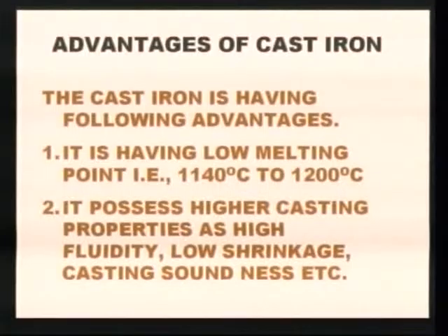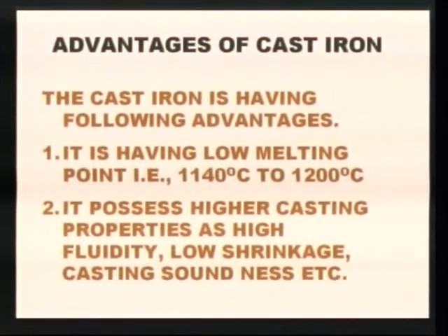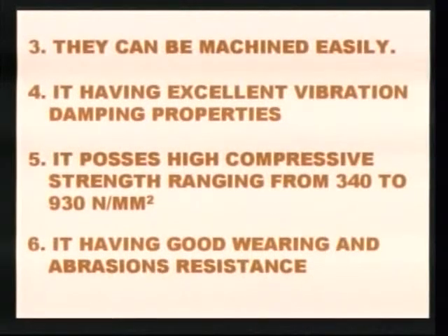First, it has a low melting point, that is 1140 degrees centigrade to 1200 degrees centigrade. Second, it possesses higher casting properties such as high fluidity, low shrinkage, casting soundness, etc. Third, it can be machined easily.